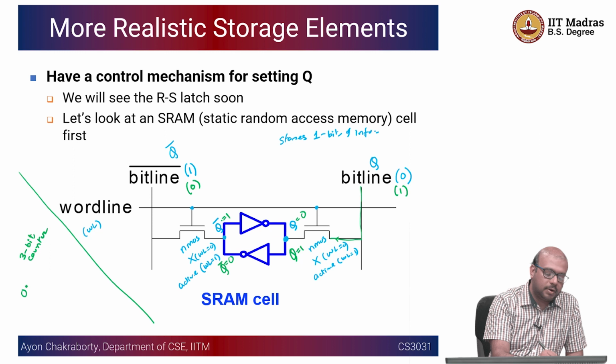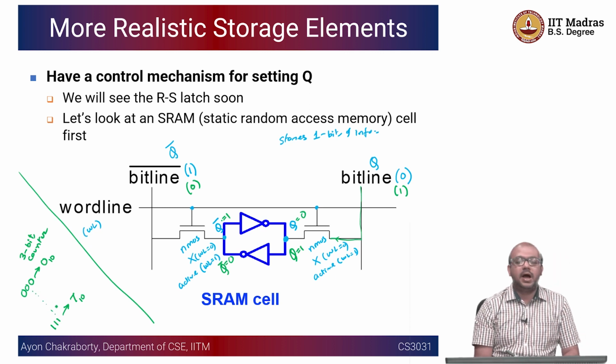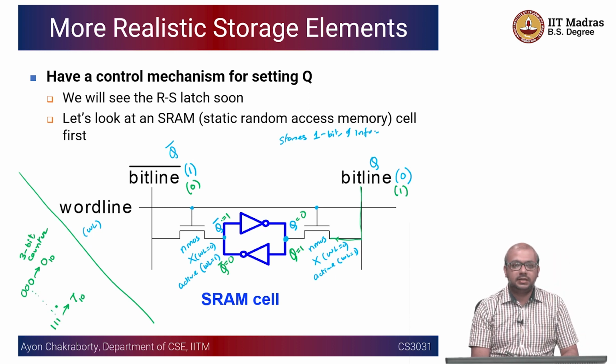It is going to count from 0, 0, 0 to 1, 1, 1. Again, going to wrap around, and this stands for 0 in decimal, and this stands for 7 in decimal, right? And it is going to count. So now if you ask me the question that what is the value of count at a certain point in time, I cannot say, right? It depends on what was the previous output.